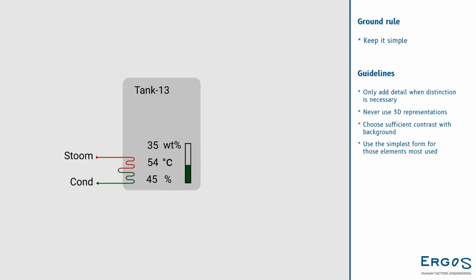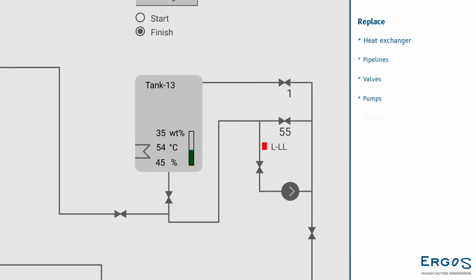The exact position of the different elements inside the vessel is not fixed. Just be sure all your vessels in the system have the same layout. In this example, we have one internal element, a heat exchanger. We just made a symbol for that. We use the same symbol here. Representations in graphics do not need to be the exact replica of the reality in the plant. The operator just needs to know that this vessel is heated. We can now replace the vessels in the graphic.